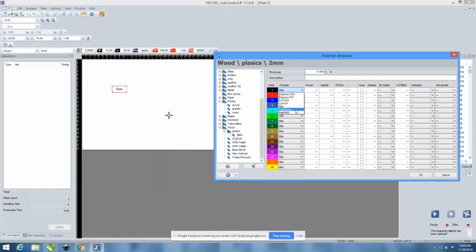Positioning is for positioning, and we have our reg marks here. We do have videos using our reg marks, using our vision camera system. You can select this so it can find those reg marks and cut your material or your product or whatever it may be. Yeah, we got lots of videos on JobControl Vision, the camera system with the reg mark. John, can you quickly just mention what positioning is? Yeah, so if you have positioning vectors and you do edit outline job, it will follow the positioning vectors rather than drawing a box around the outside of the area to be engraved. Perfect, thanks.